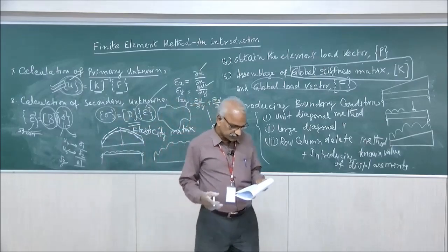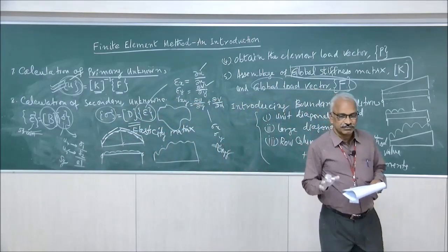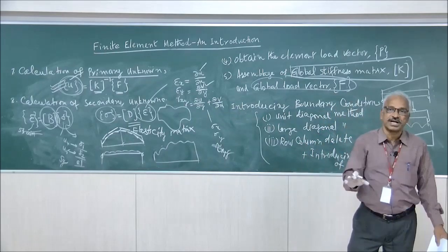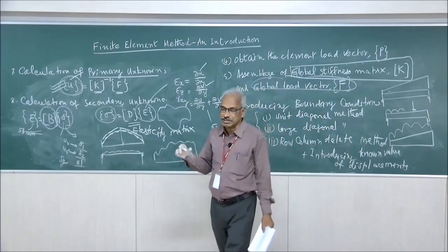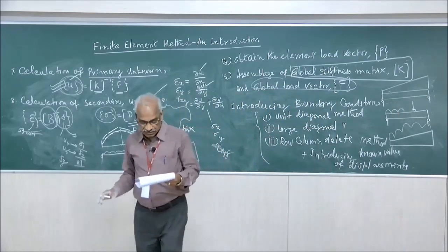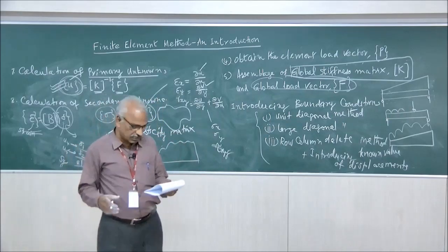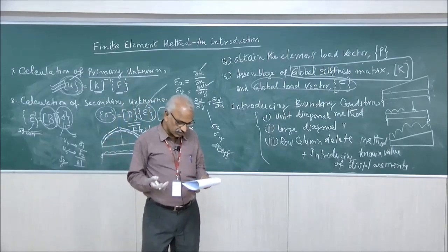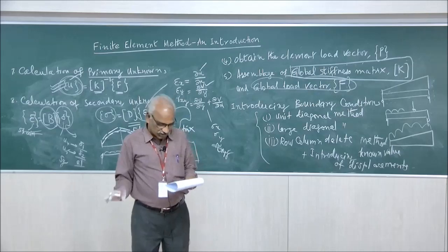And coming to the disadvantages, if proper physical comprehension or physical interpretation of the problem is not possible, then this will not give the true result. That depends. There are many chances for this. The K matrix may be singular. If the K matrix is singular, then a solution is impossible.